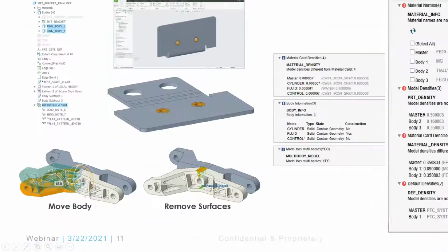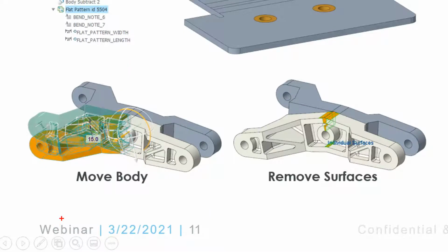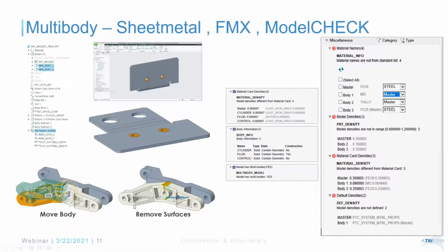Maybe some of you may be using the flexible modeling extension, wherein you get some imported geometry, or even for late-stage design changes, you don't want to go through the typical edit definition. You want to do a quick move, right? You want to do a quick change, some shape recognition, and do quick moves. There also you could use the flexible modeling extension.